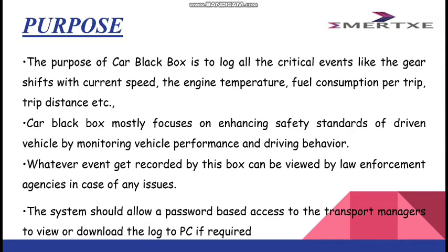The basic purpose of a car black box is to log all critical events like the gear shift with current speed, the engine temperature, fuel consumption per trip, trip distance, etc. A car black box focuses mainly on enhancing safety standards of the driven vehicle by monitoring vehicle performance and driving behavior. Whatever events get recorded by this box can be viewed by a law enforcement agency in case of any issues. The system should allow password-based access to the transport manager to view or download the log to a PC if required.